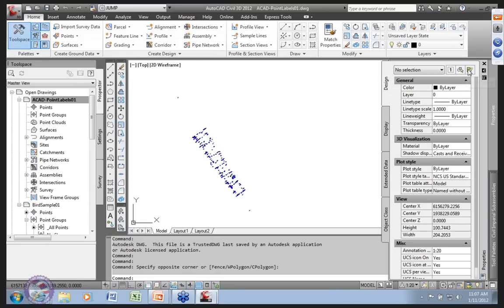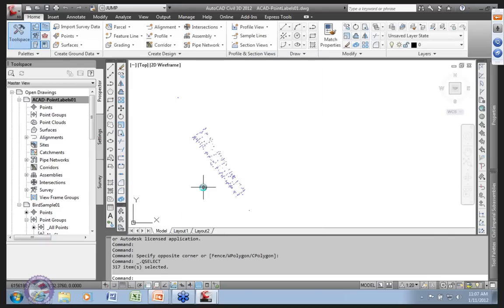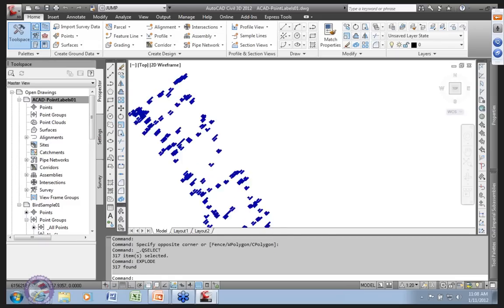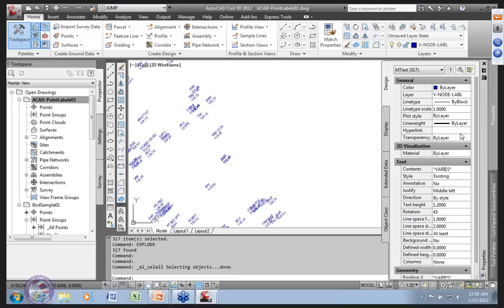And this is also a good test, which is why I do it this way. Okay, I've got nothing but those block references in my drawing. I want to select them all, and make sure I didn't pick up something bizarre from somewhere unseen. Okay, and I got all those guys, and we want to, of course, explode them. All right, and now what do I got? If I do a Control A, this fast way, grab everything in my drawing, I end up with all MText.